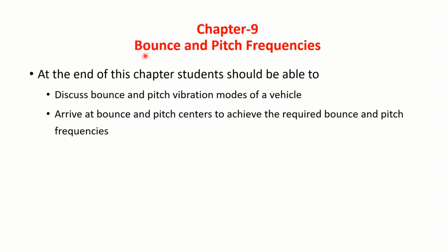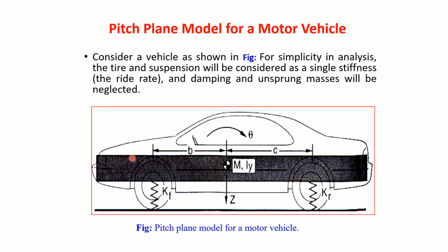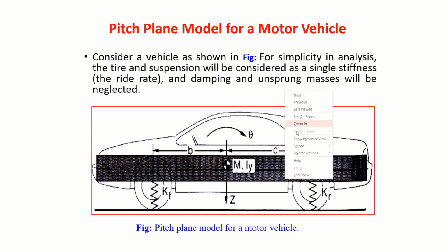In this session, let us discuss bounce and pitch frequencies. So, we will be discussing bounce and pitch vibration modes of a vehicle, and we'll arrive at bounce and pitch centers to achieve the required bounce and pitch frequencies. So for that, let us model the car in a longitudinal direction.